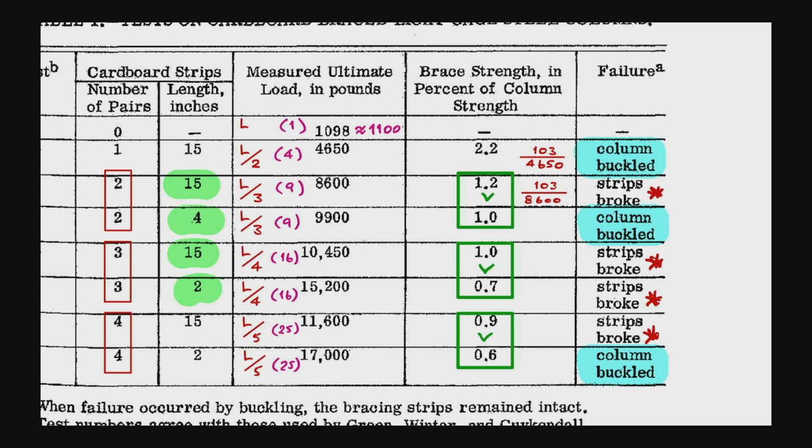The machine reading, the gauge, all these testing instruments generally cause some error, especially at the low load zone or low load magnitude. If you have the equipment that measures a very wide range of force magnitude, for example, if you have the load cell for 100 metric ton,